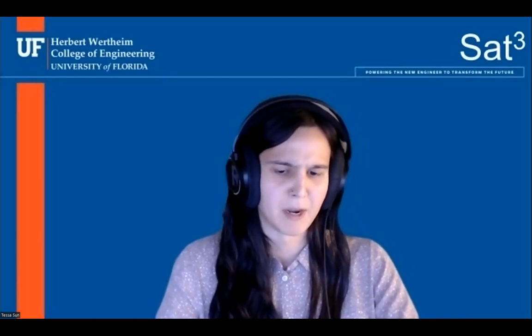Sorry. I literally went to my slide that has the maximum force of the spring when it's compressed by the CubeSat, and I took that force and divided it by 25 kilograms, and that would be 10.94 meters per second squared, so a little over a G. Okay. So assuming it's fine on Earth and through launch, it should probably survive being pushed out. So as long as it can withstand that, it should be fine.